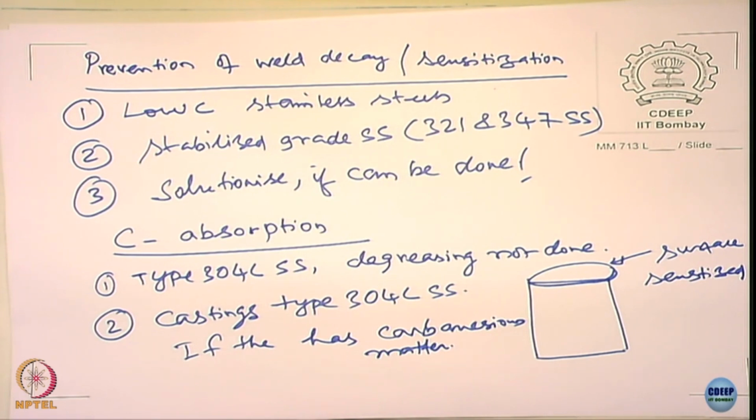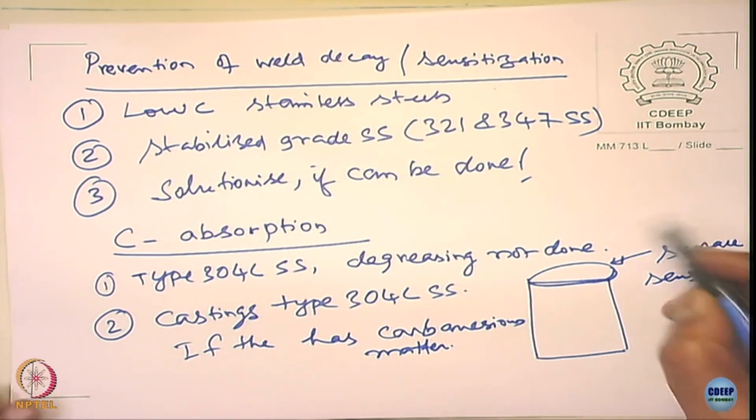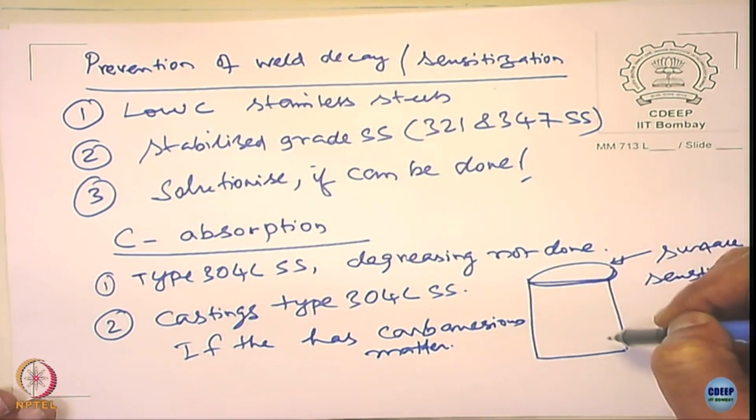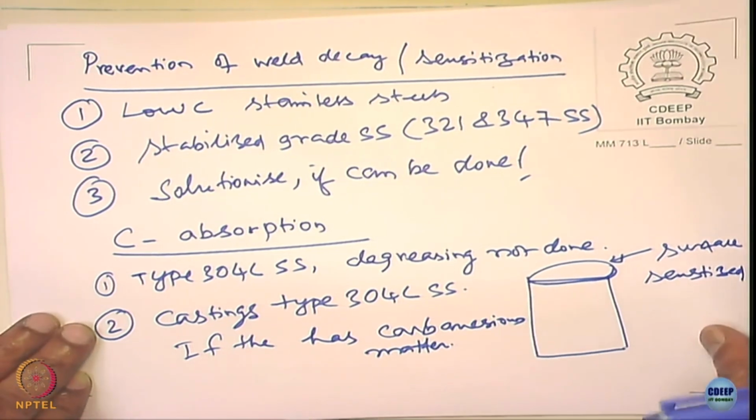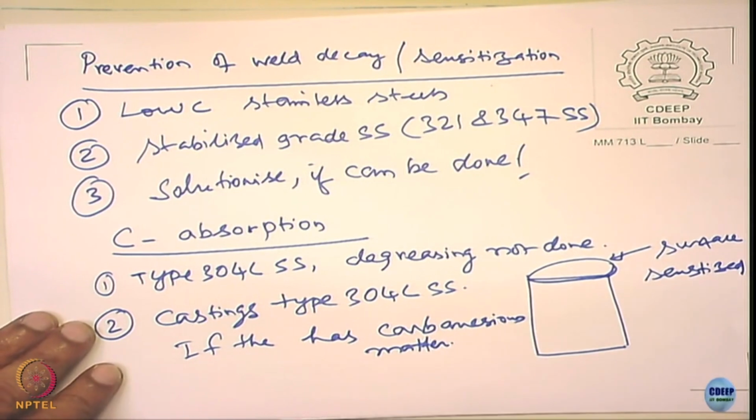It depends on the mold, but that is why it is only on the periphery, not in the center. You can shave off, it can happen, or a better way is to go for a ceramic mold or something which does not give away carbon. So, you see sometimes it is happening, and so you must know how to tackle the problem.